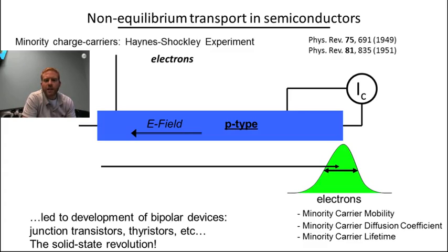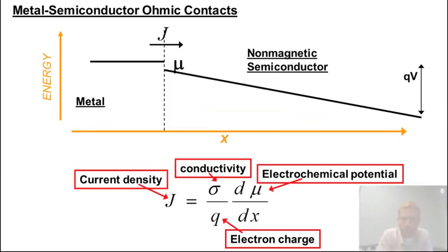So, if we speculate any use for spin-polarized electrons out of equilibrium in semiconductor devices, then we at least need to be able to measure the spin analogs of these parameters. So let's first look at why it's not so easy to transfer the substantial spin imbalance, spin polarization, from a ferromagnet into a non-magnetic electronic material, especially when using a semiconductor in an effort to make, for example, new kinds of spin transistors. The most straightforward way one might naively try is to make an ohmic or linearly resistive contact between the ferromagnet and a semiconductor.